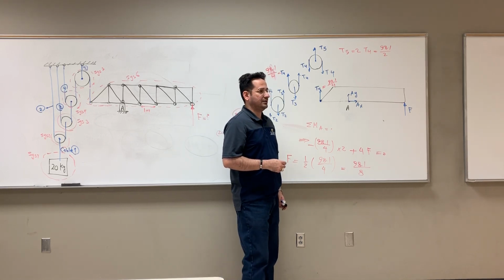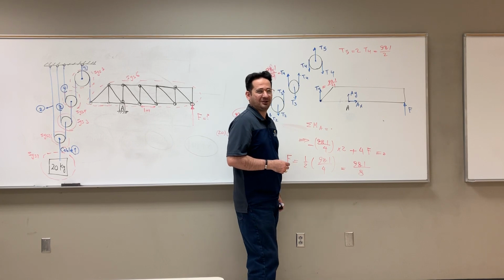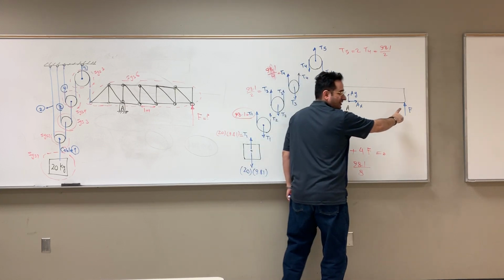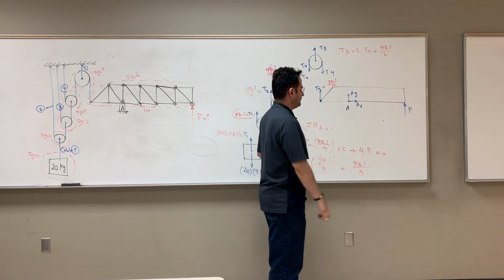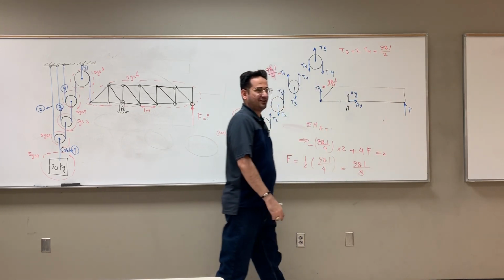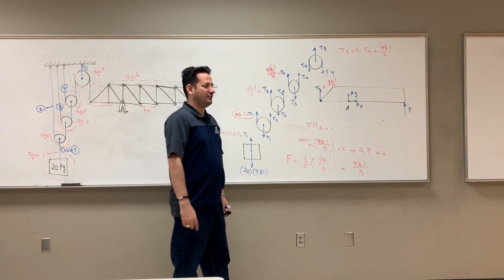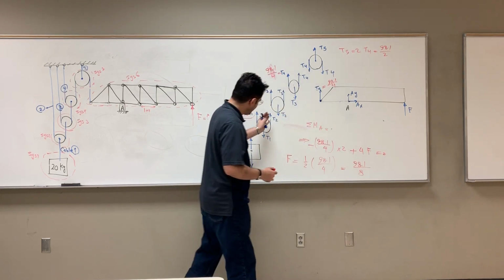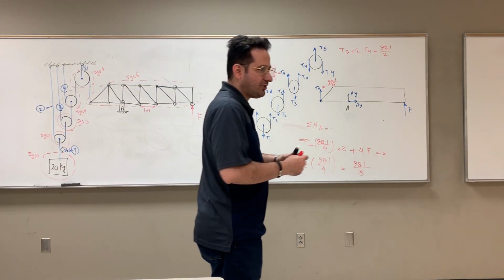Yes, that's one way. Another way, summation of force in y direction is 0. Right? You already have this. You already got this guy plus AY is 0. And then AY is just this plus this with a negative sign. You see that? So what I'm trying to say is, always read the question, because sometimes you may have just 1 or 2 lines and you can just get rid of that problem and go to the next one.